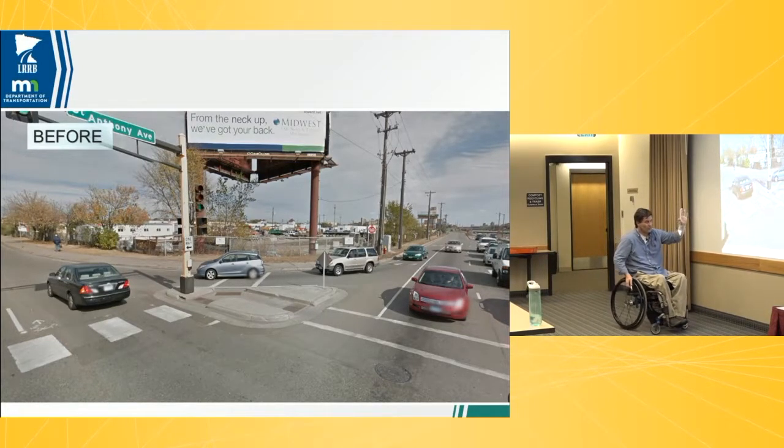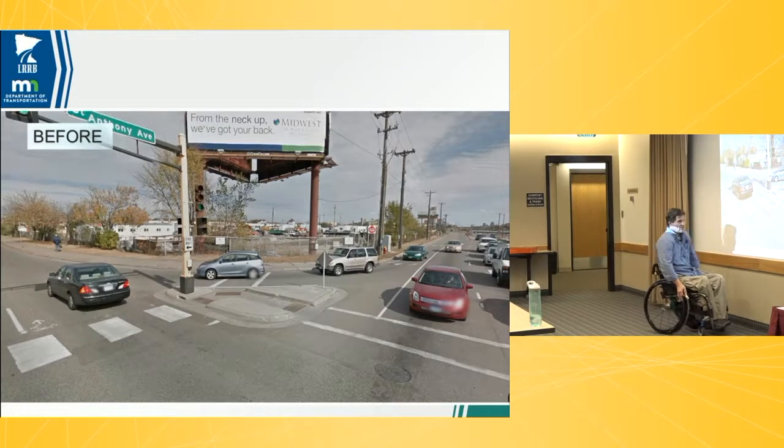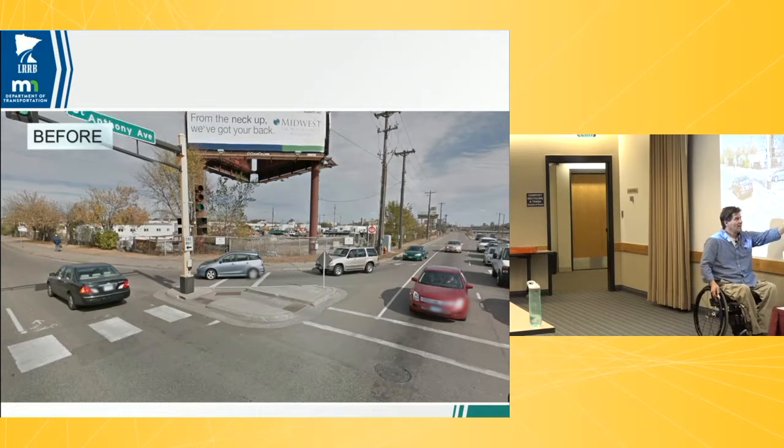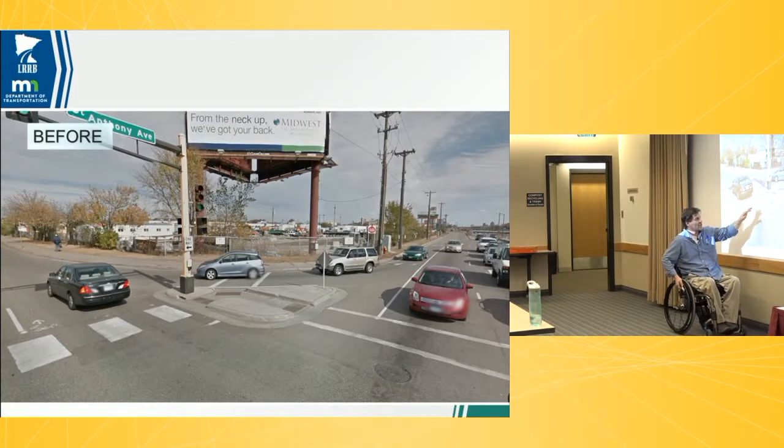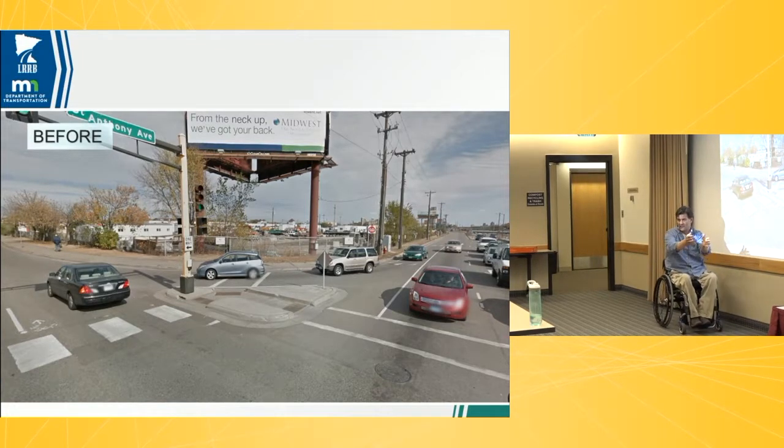But so what can we do out here? First of all, I start looking at this area. This is all right turn lane, and what's this? This is nothing. This is ripe for the picking right here. I can make that pork chop a lot bigger. Also, there was a need for some channelization here, or just cleaning up the lanes, so the pork chop can get wider this way too.